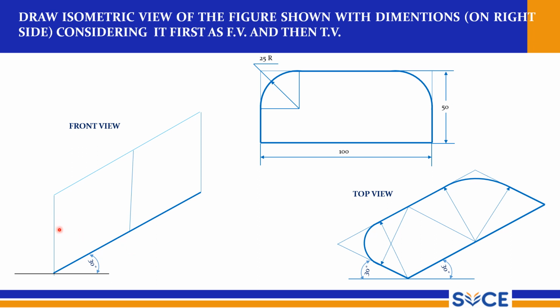And now this is the smallest, this is the corner which is compressed, right? So now you can use 4 centers. This is the smallest diagonal, so here we will start. This is the smallest diagonal, and this is the longest arc. So this should be used as center, and this much as radius. Draw the arc between those two center points.